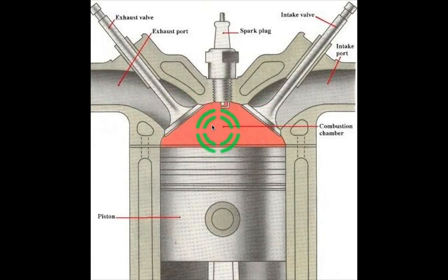Please remember that not all combustion chambers look like this. This one, they call it the dome or the crown kind of combustion chamber. Then they have a flat one, which is seriously flat. The valve is just going to touch it. There is no room. That's what they call an interference type and non-interference type head. Let me not discuss that. Go and look for it yourself, because we have nothing to do with that. It does not affect the efficiency at all, at least to what I know. So we will not discuss it. Okay, so much for that. We've finished the combustion chamber, how it looks.